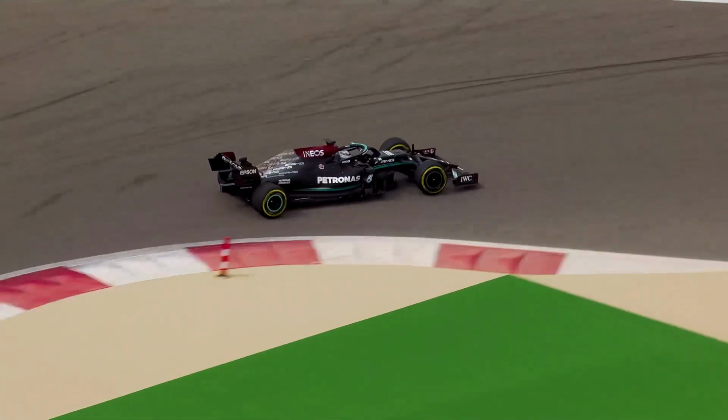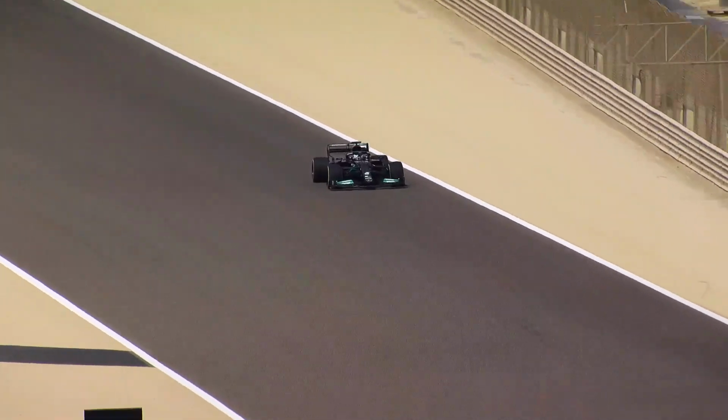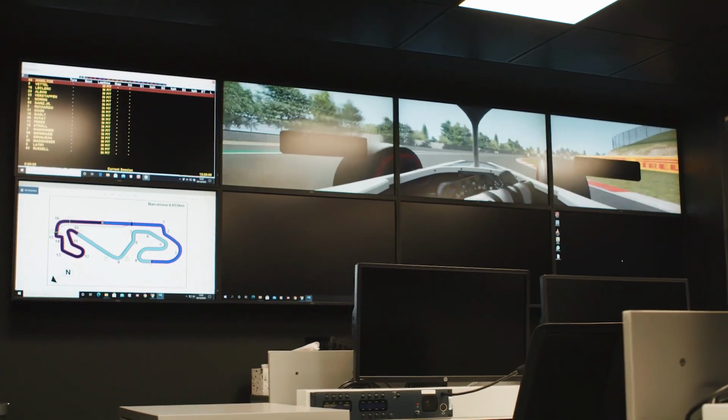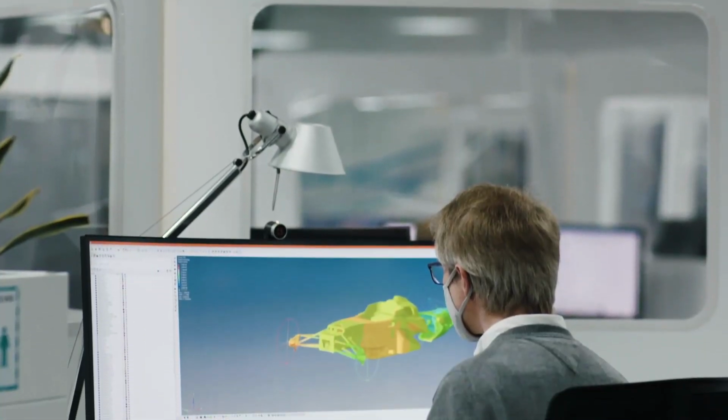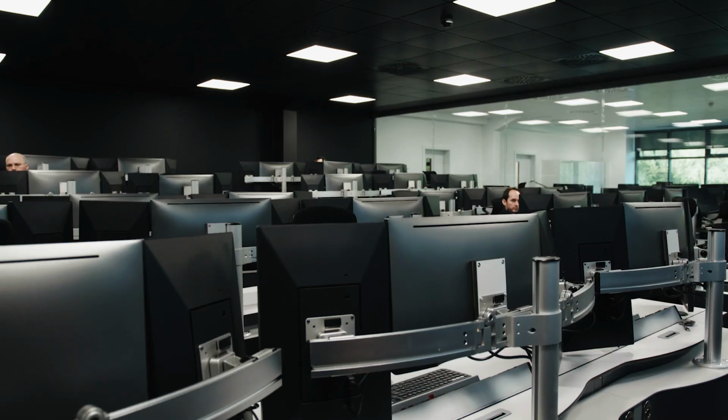With the very limited testing time in Formula 1, it's increasingly important to start the race weekend with a good setup. Simulation results can also be cleaner than testing components at the race weekend due to many factors such as traffic from other cars, weather changing, the grip changing during the race weekend, and lots of small factors that mean that even the best racing drivers in the world would have difficulty picking out those small differences. Using simulation tools, we can see many small differences by sweeping many different components, which allow us to define the best overall compromise for the vehicle for the race weekend.